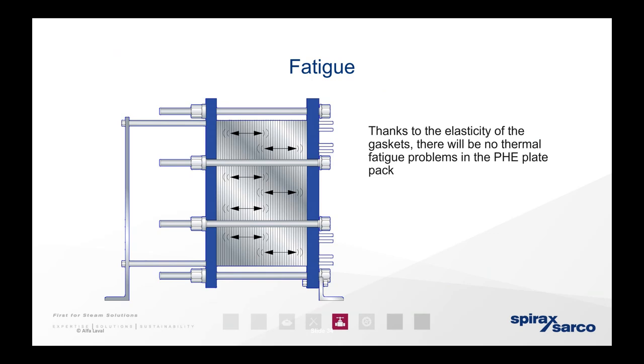They will wear out. So depending on the usage of your heat exchanger, we would recommend inspection probably every 3 to 4 months, replacement of those gaskets every 6 or 12 months. Again, it's very process dependent. If these things are being heavily used, you'll need more maintenance schedules. If they're relatively constant loads with little or no fluctuation, they're going to last longer.